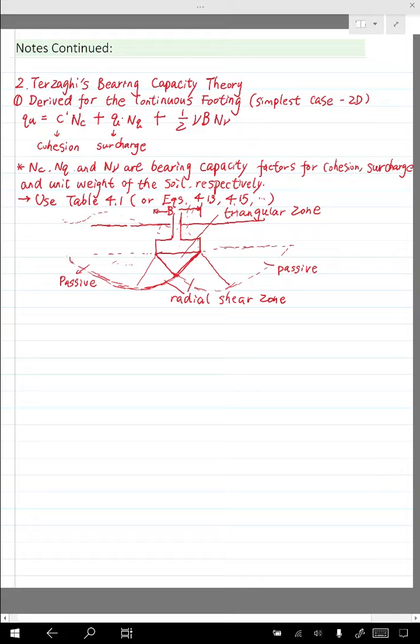And the Q that we mentioned actually is the vertical stress here. So this is the surcharge. It's not the pressure on the top, it's the pressure here. So Q actually is sigma Z0 prime, again, the effective vertical stress at this depth.